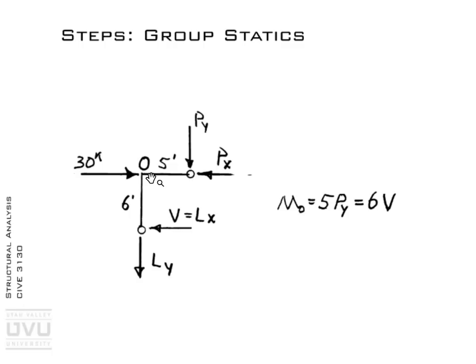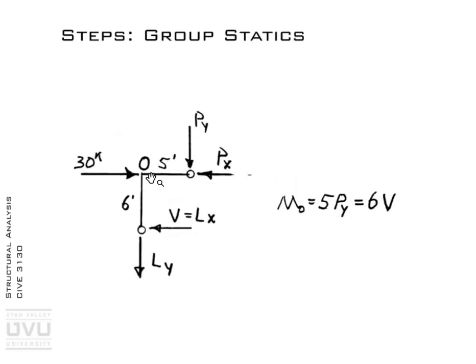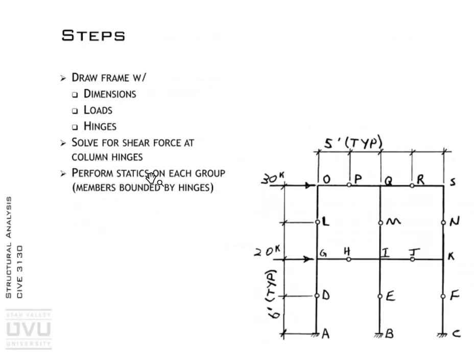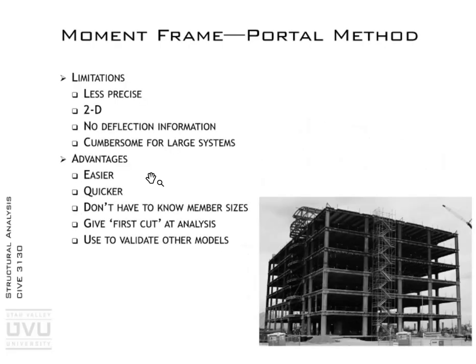So it turns out to be a really effective method to quickly analyze a big moment frame and just spot check some of my results from an analysis. Additionally, maybe you're in a preliminary design of a building and the architect says, hey, what do you think those column sizes and beam sizes are going to be?